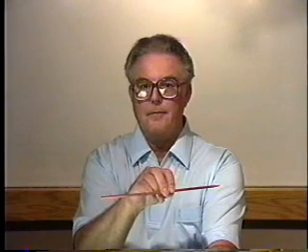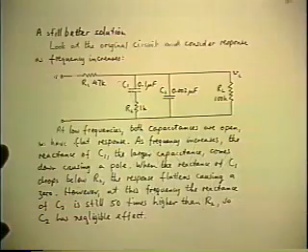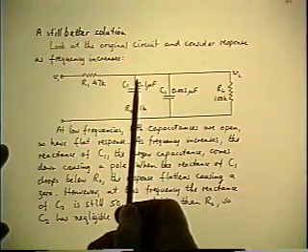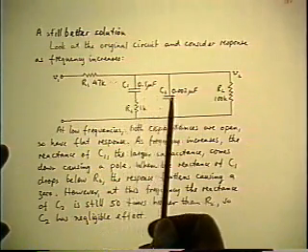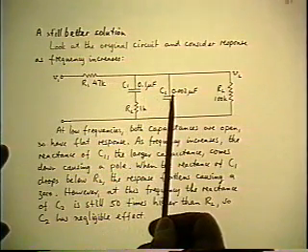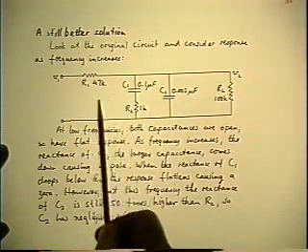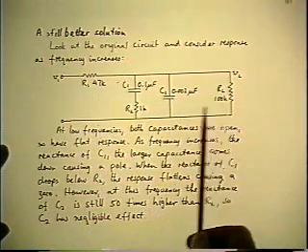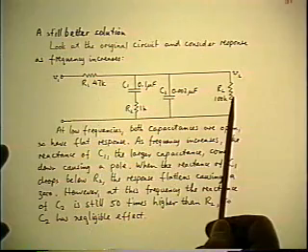That's a 0, a concave upwards corner. Again, dominated by C1 only. At that point, the circuit is now such that C1 acts as a short and C2 is still open. So you get another flat gain corresponding to a different resistive divider, where R2 is in parallel with RL in the bottom branch.